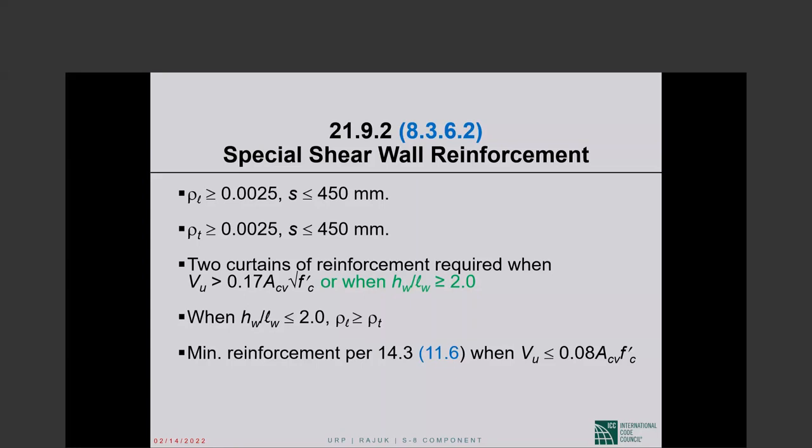The remainder of the shear wall length, we provide the horizontal as well as the vertical shear reinforcement. Okay. The concentrated flexural reinforcement at the ends is confined. We have hoops around them.